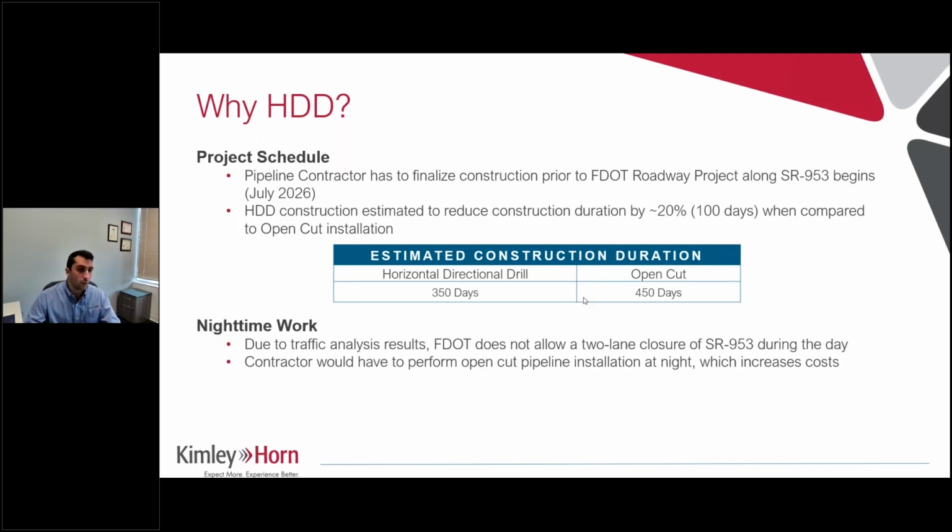We coordinated with them, and ultimately we were told we have to put the pipeline in before their project goes through. So we evaluated the open cut versus drill option, and we estimated about 100 days of savings in construction time. We expect this project to take about 350 days in comparison to the open cut portion being 450 days.